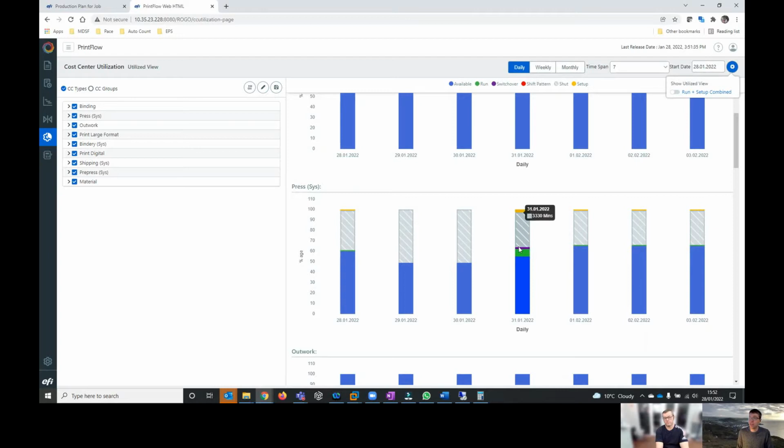And you can see there's a 40-minute switchover here. Something is needed that's going to cost me time in production. Maybe you need to wash up blankets. You've got to change some packing on a press because you're going down to a smaller sheet. That kind of stuff, you can build rules into it and build it as part of your system. So it says, if the next job is a different type of job, then do this thing. Or if the previous job is a different sort of job, then do this. So it knows about the relationship between the jobs that are next to each other?